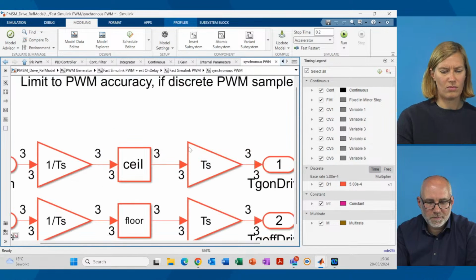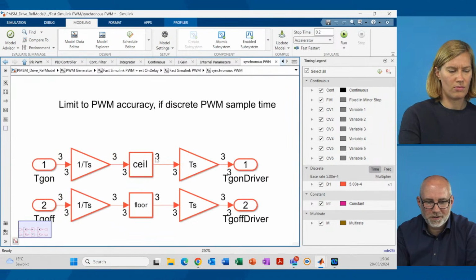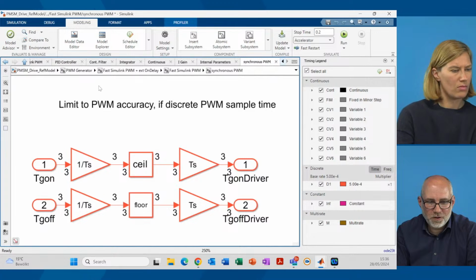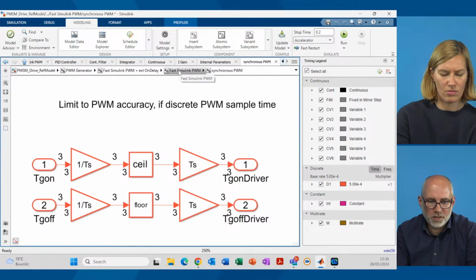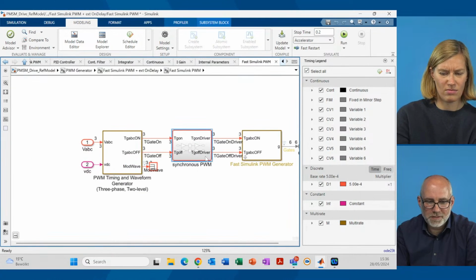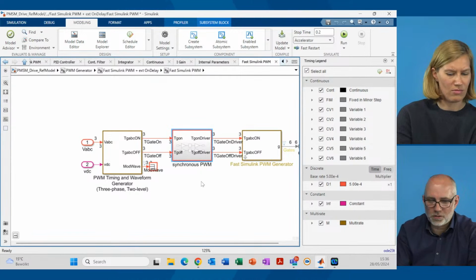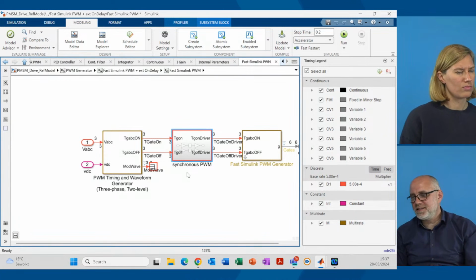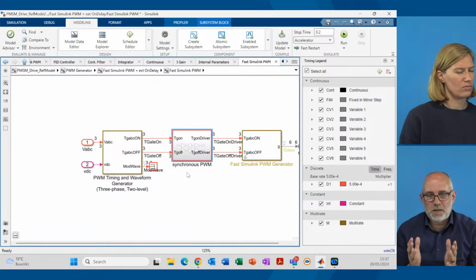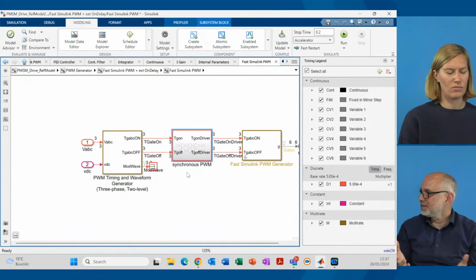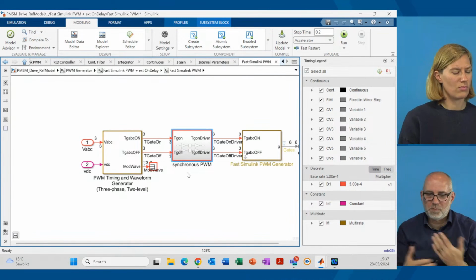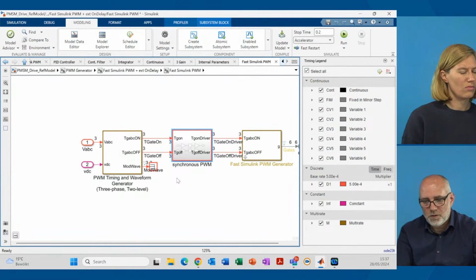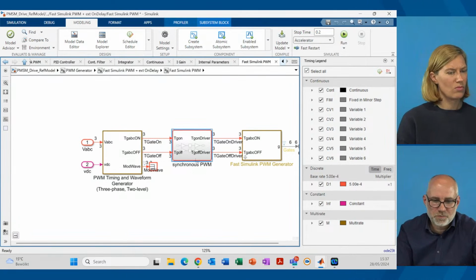Then, yeah, there's some tricky part in here. Just for compatibility reasons, I wanted to have this PWM compatible with the setup before. We had a discrete timing before, and even in realistic implementations, you have a PWM circuit, a digital circuit, where you have to program a register, for example, for a specific switch on and switch off time.